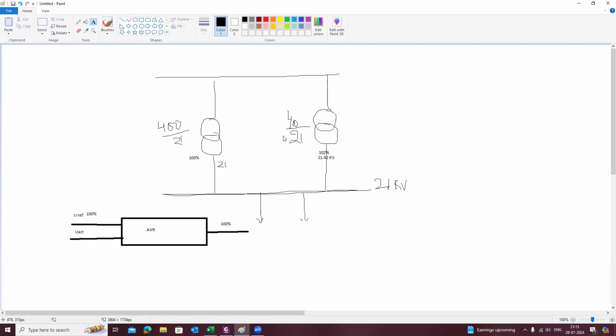I'm asking like that. See, exactly. If you take the case of large generators, in the megawatt capacity range, then probably 100% and 102% does not create that much of a difference, because you have the reactive power limit. There is a term called the generator capability curve, right? So if you see the capability of large generators like 500 megawatt, 660, 800 megawatt generators, you have a capacity margin of minus 200 MVAr, 300 MVAr, something like that. On the lagging side, you have some 450 MVAr also. So that means if the reactive power flow in the generator is well within the capability curve of the generator, there is no issue at all.